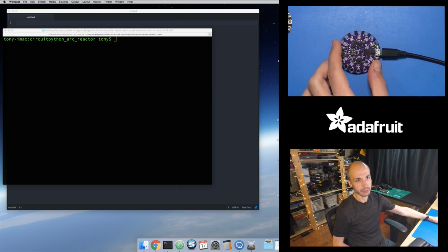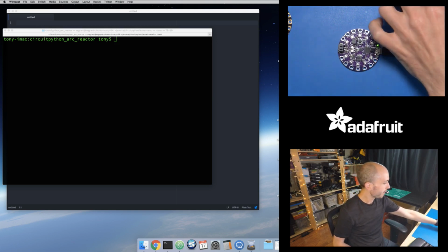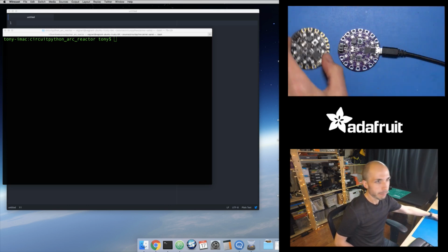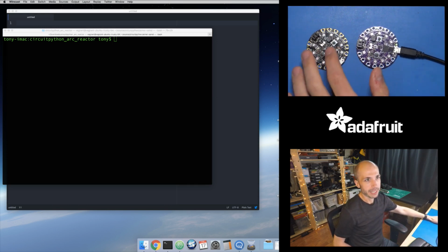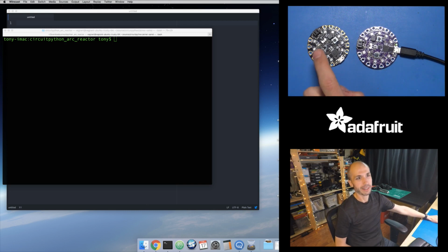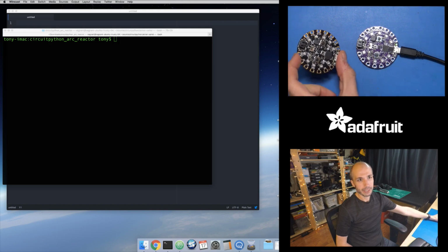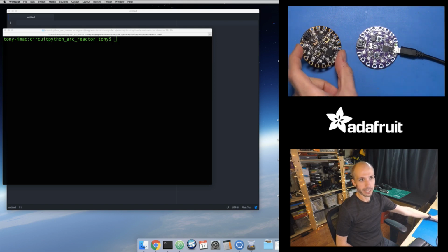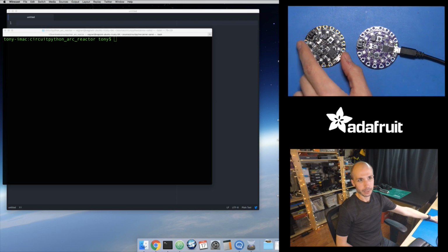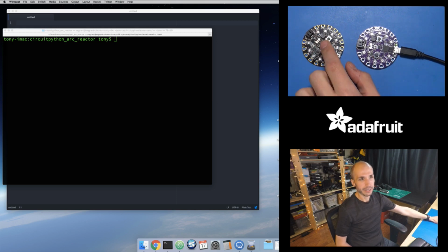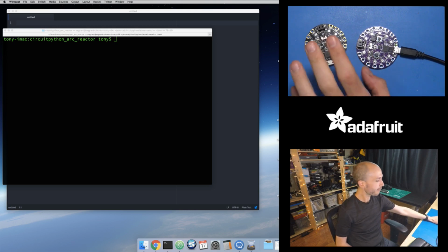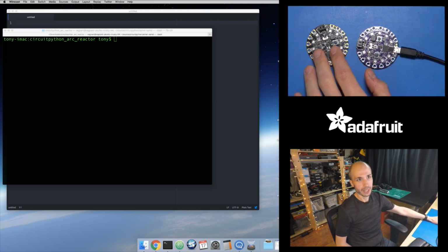It's actually loaded with CircuitPython right now. So this is almost exactly the same as this Circuit Playground right here. This is the classic Circuit Playground, I guess I'd call it, which has the ATmega 32U4. But this one you can only program with Arduino. You have to use that C-based Arduino language, and you can't really interactively program it. You don't have the Python REPL and things like that that you get with MicroPython and CircuitPython. But same features as far as what's on the board.